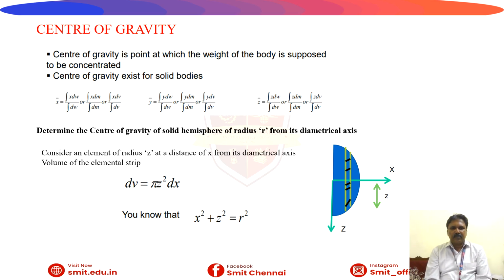Then center of gravity. Center of gravity is a point at which the weight of the body is supposed to be concentrated. Center of gravity exists for solid bodies only. X bar equal to integral of x dw by integral of dw, or we can write integral of x dv by integral of dv. Similarly, for y bar, replace x by y: y bar equals integral of y dv by integral of dv. Similarly, z bar equals integral of z dv by integral of dv.